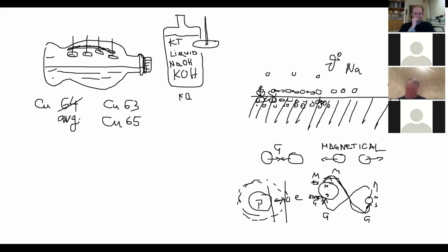In which case, for instance, you can fill a special or electric oven with nitrogen gas. You put the metal parts in a crucible, you fill the crucible with nitrogen and seal it, and then you heat it up to 600, 650 centigrade and keep it for 8 hours. You will find such nanowires growing on the surface, which are, for instance, excellent for supercapacitors.